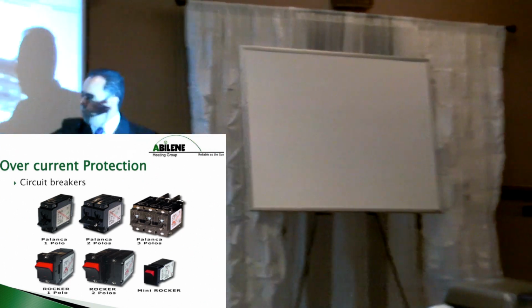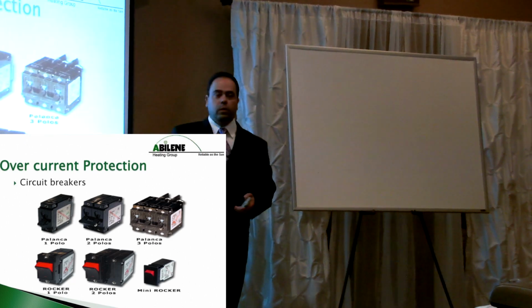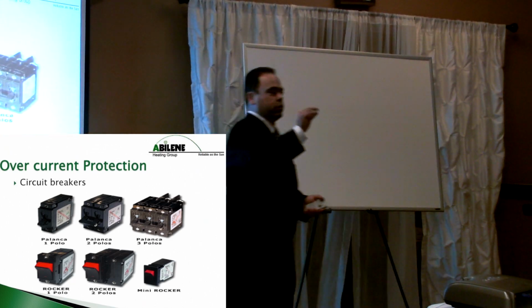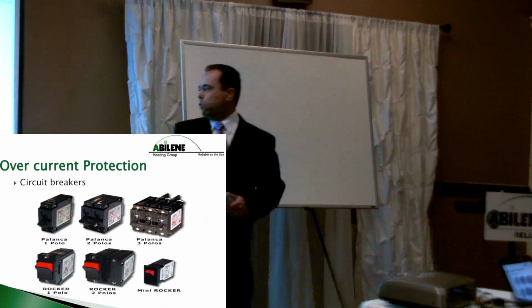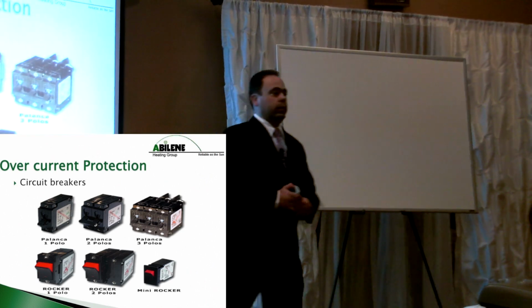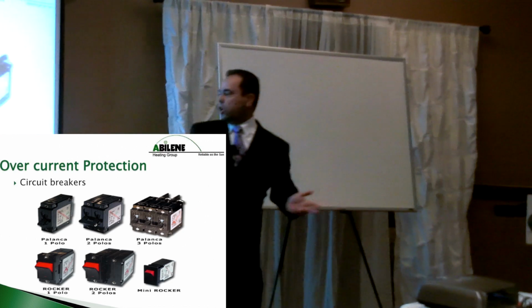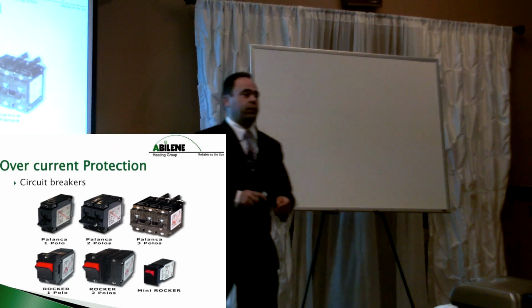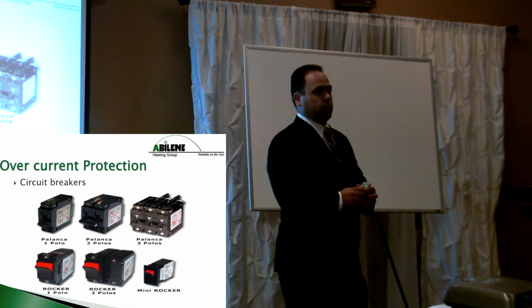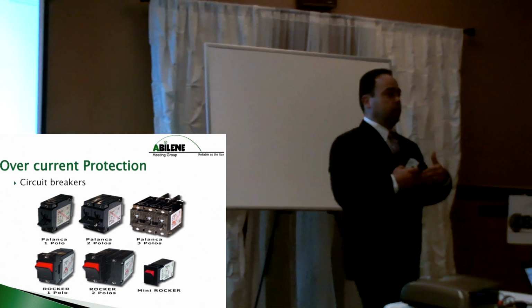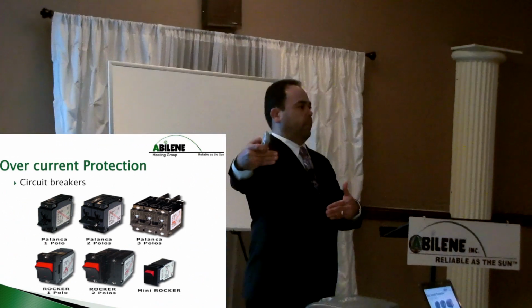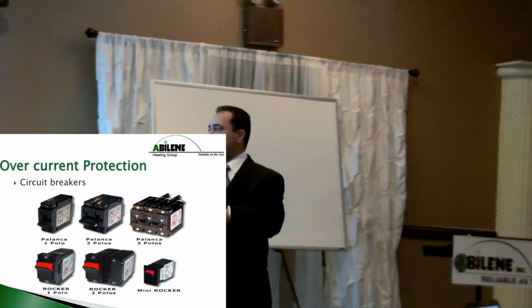These are also types of breakers. You'll see them in the burner cabinets. They're little rocker switches, but they're run on one side. They're a mini breaker. A lot of times you'll see them sized at 10 amps, they might be sized at 15 amps. All right? They're protecting everything downstream of them. And we're going to get down to how they work.